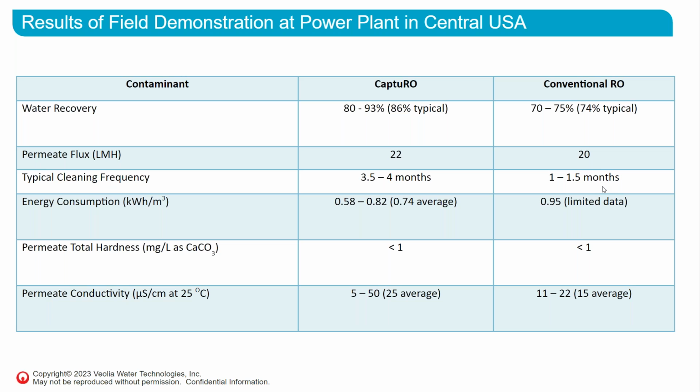Now you might ask why. It's river water, UF pre-treated, but the UF system they had at this plant was not in the best condition. Their hollow fiber membranes were breaking a lot of the time, and we were getting a lot of solids coming through due to breakages in the upstream UF hollow fibers.